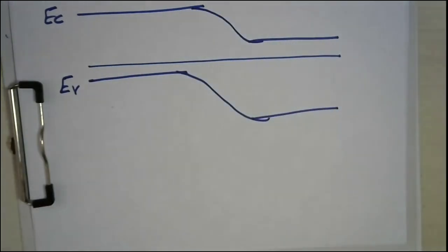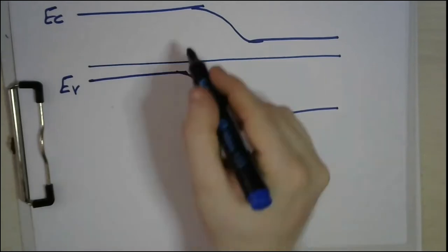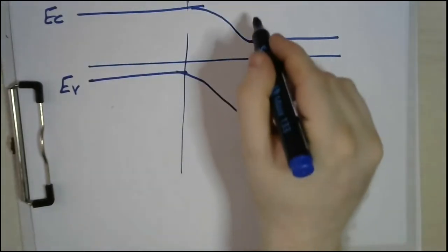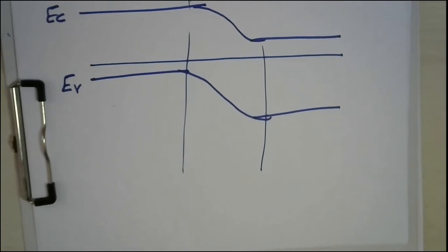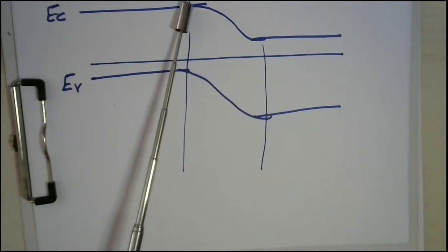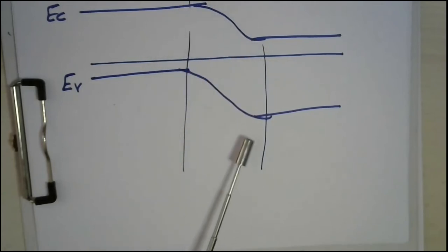Okay, perfect. This is an energy band diagram for a thermodynamically equilibrium PN junction. Now we have what we call the internal drift. This is the built-in potential. The sign for this built-in potential is simply that we have a tilting in the energy band diagram, as you can see in this region, and as you can see also in this region. Perfect.